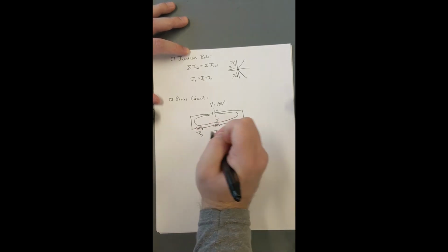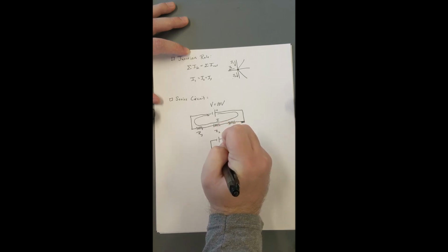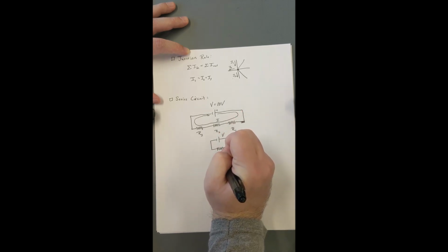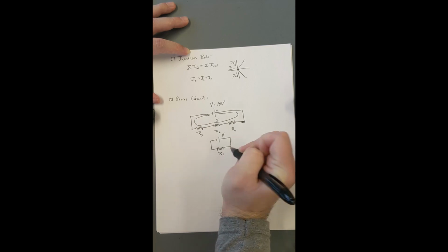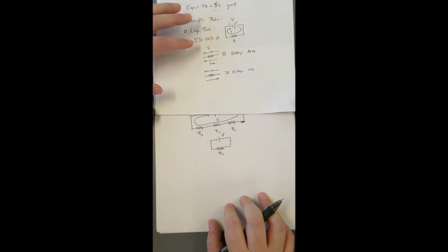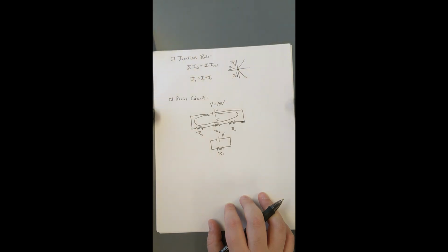All right, so if we were to find a total resistance of this circuit, say if we combined these resistors 1, 2, and 3 into a total resistor R sub S, we first apply the loop rule that we discussed before here, that the sum of all voltage rises, subtracting off all of our voltage drops, should give us 0. So let's do that.